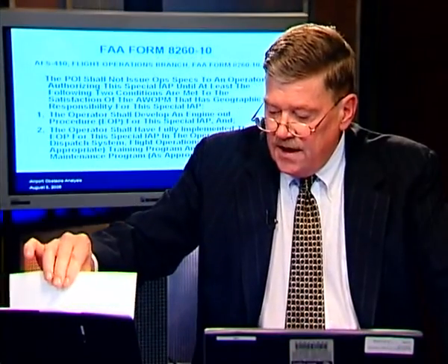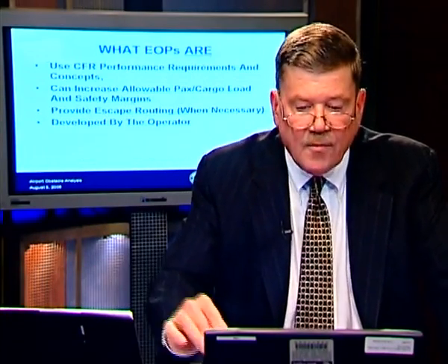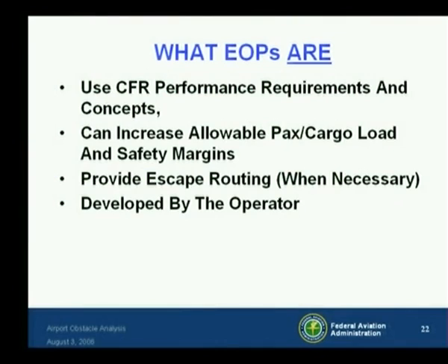We've seen what EOPs are not. Now let's take a look at what EOPs are. They use the CFR performance requirements and concepts, the airplane flight manual information, and other aircraft performance data. They can increase allowable payloads and cargo load and safety margins. The primary reason for developing these procedures is to maximize the takeoff weight for the carriers and to maximize the safety margins for the FAA, for us.